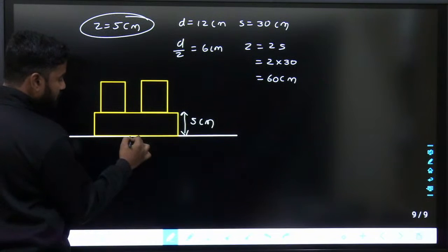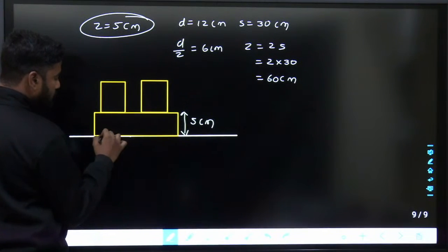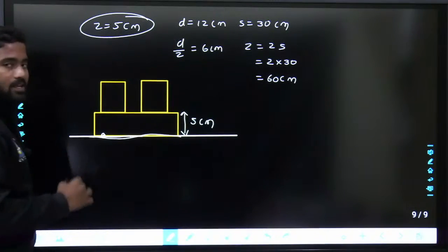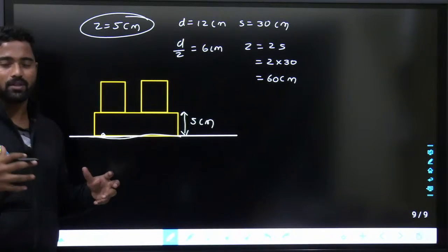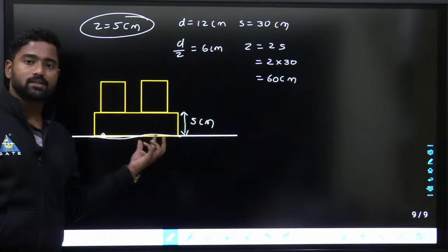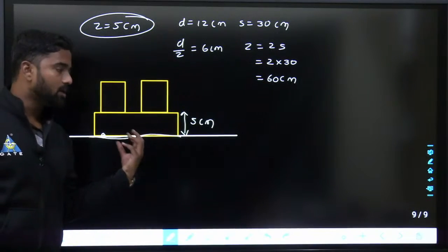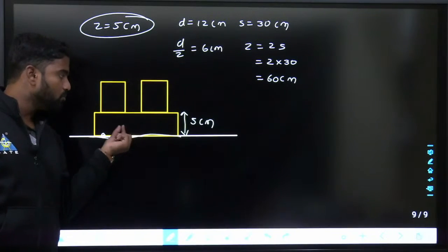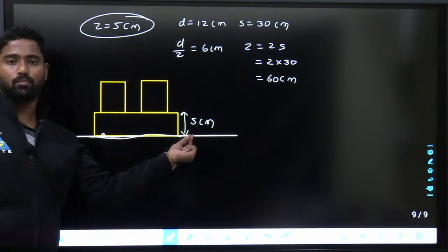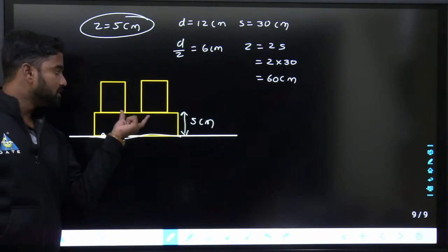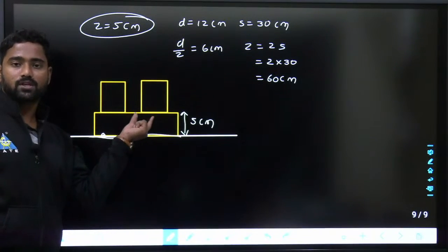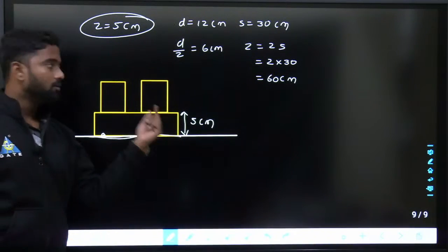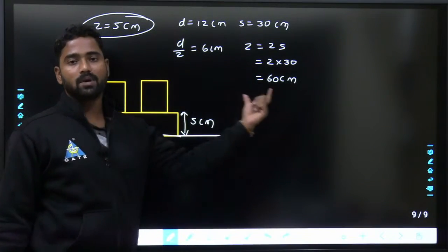The stress at the end of the pavement, indirectly the stress at this line, should be within limits. I told you initially, stress at the soil subgrade should be within permissible limits. So we are more worried about stress at the topmost position of the soil subgrade. This is pavement, with surface coats, subbase coats and all those things here, and this is soil subgrade.